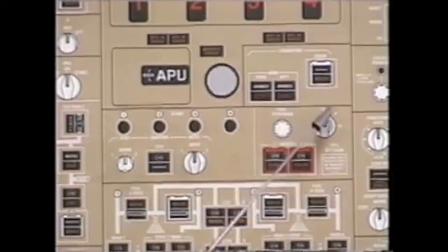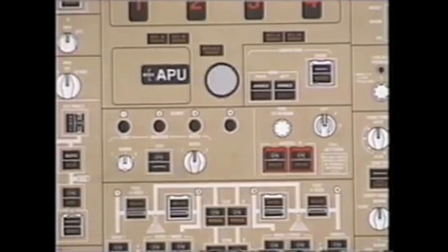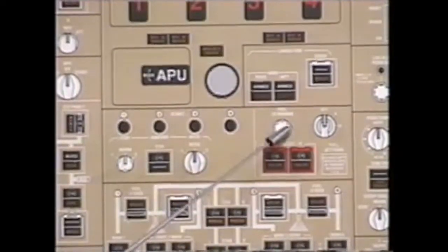Fuel jettison controllers A or B, we will select the desired system. When you do that, fuel temp on your lower right-hand corner of your primary ICAS is replaced with fuel to remain. That value can be increased and or decreased with the fuel to remain selector.